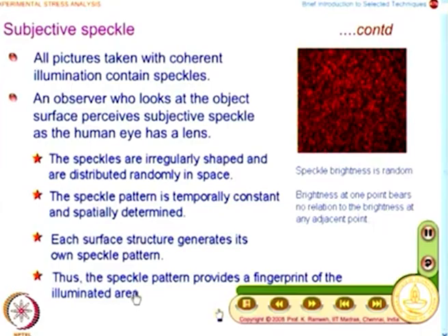In the case of moire, we put a grid on it which is regular. In the case of speckle, you have these speckles formed that act like a fingerprint, and that is why we also said speckle provides you fringes which are not very smooth. We saw that when we looked at the out of plane displacement of a plate clamped all around the boundary with a central load. The experimental fringe pattern which I showed was from speckle interferometry. It was not as smooth as what I saw in photoelasticity, it had only points.